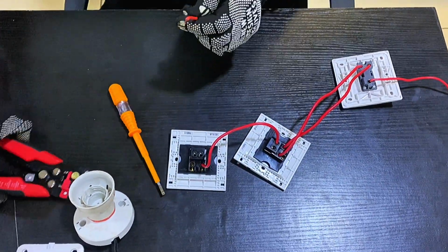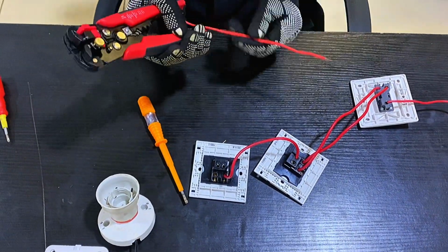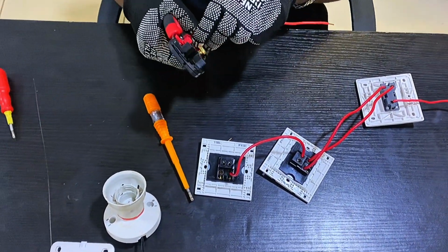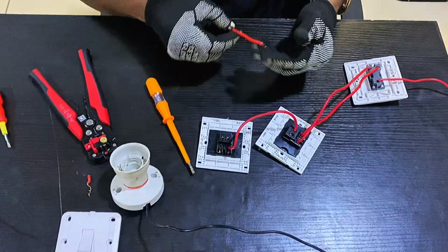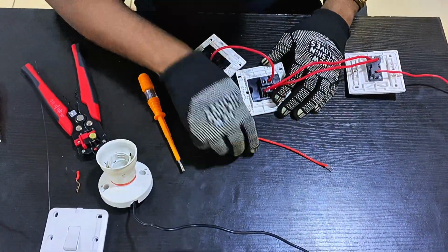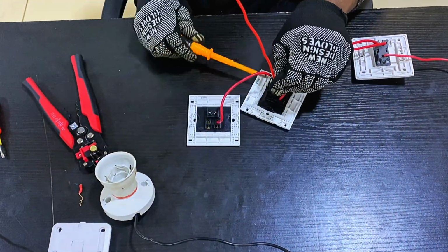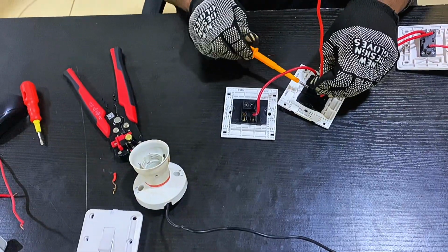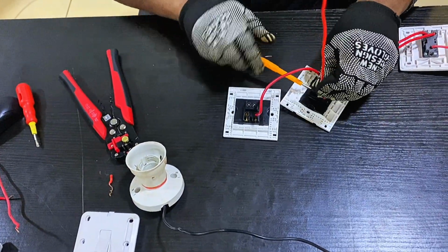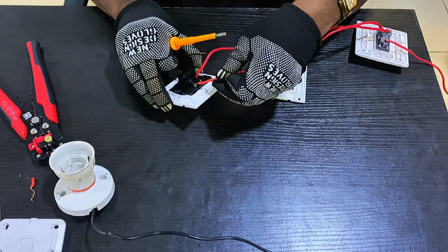Take the next stripped cable. Ensure that your terminals are not too long so that it doesn't get bridged along the line. So you only strip what you're supposed to use. So you come here now for your 4. You take your 4, connect it tightly, and take it to your 2.